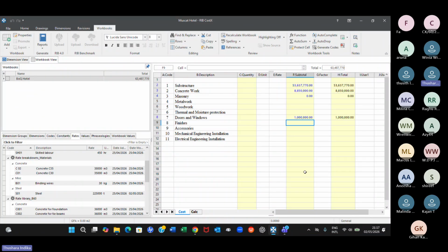So you have to measure the reflected ceiling from the ceiling plan, flooring from the floor finishes, and walls from the wall finishes. You just measure the area, and then create dimension groups accordingly, and then you have to put into the BOQ. Simple as that. So don't expect me to measure finishes, because that is why I have taught you how to do the area measurements. Okay.